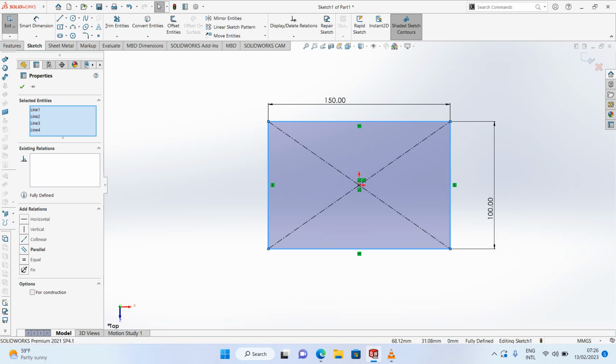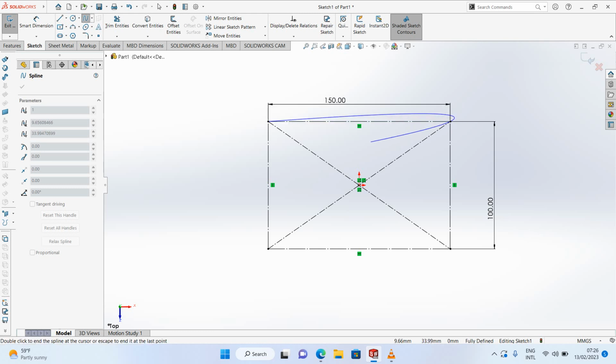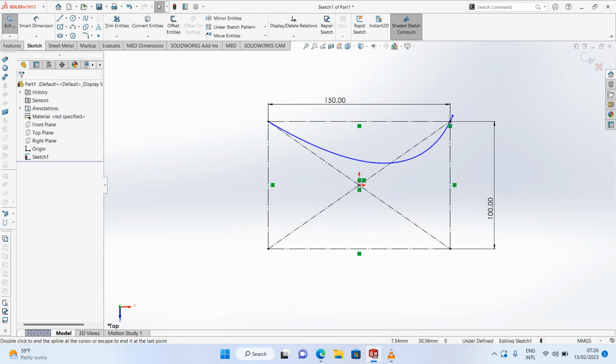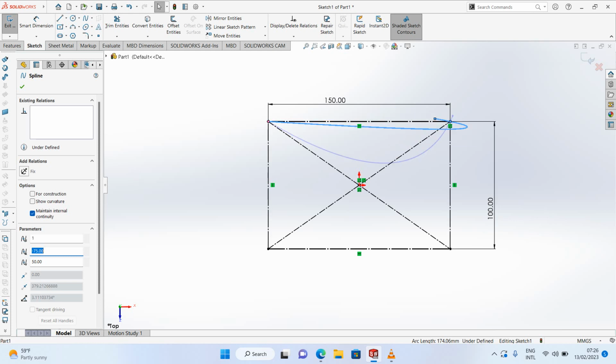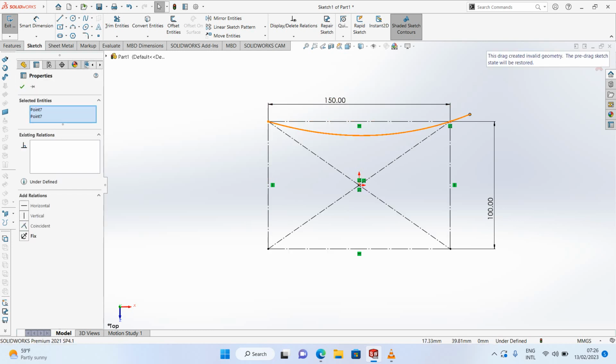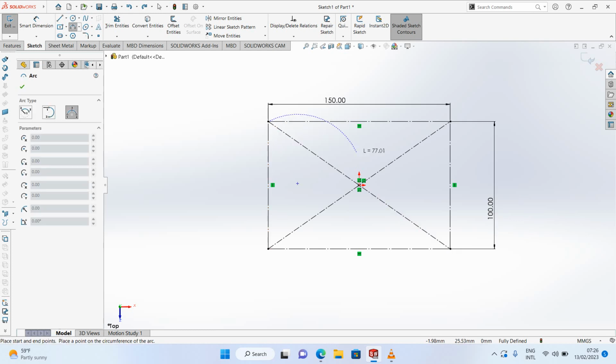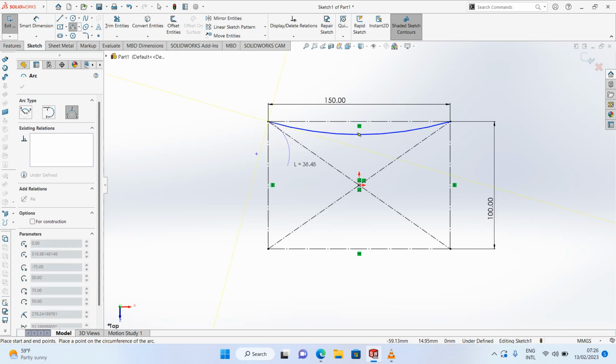Make it for construction because we want to create an organic shape like a ketchup sachet. We use this type of spline, the freeform spline, just to create such a profile that will mimic a ketchup. So, Control Z, sorry for that. I think we'll use this one, it will be more flexible. So I take a 3-point arc because it will give me flexibility while sketching.